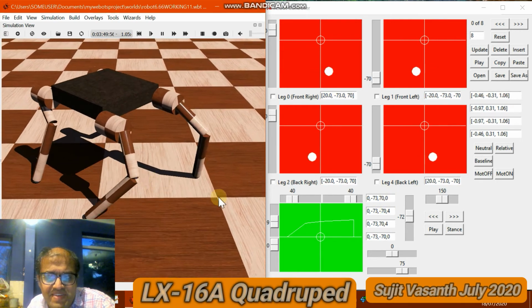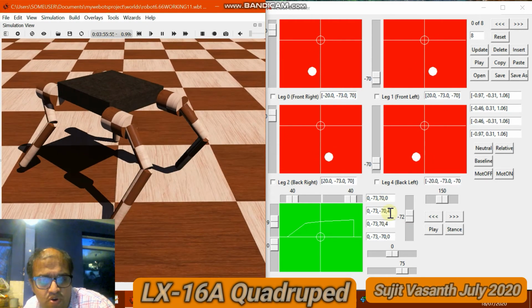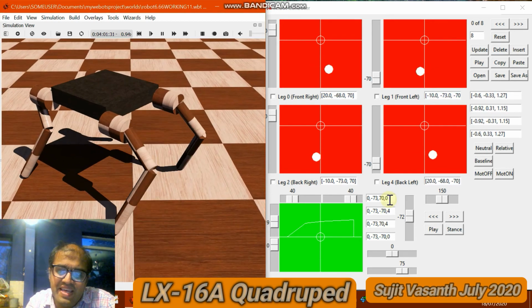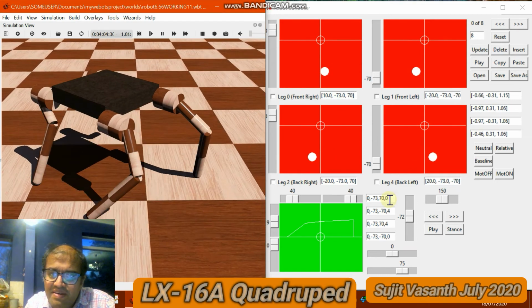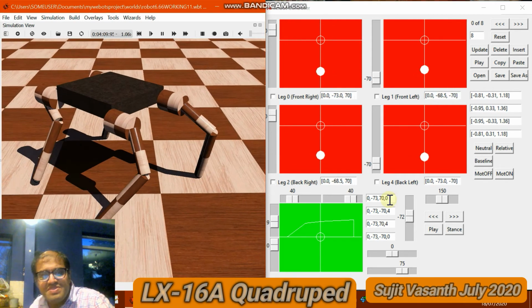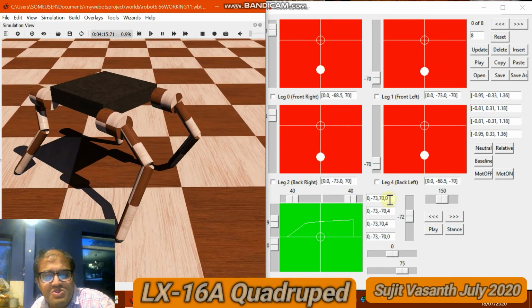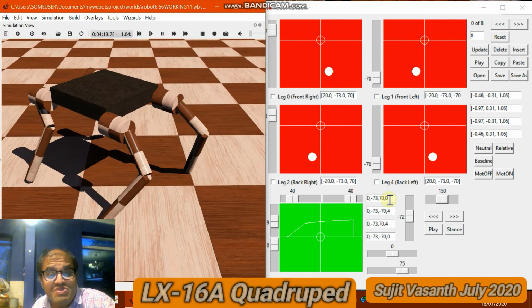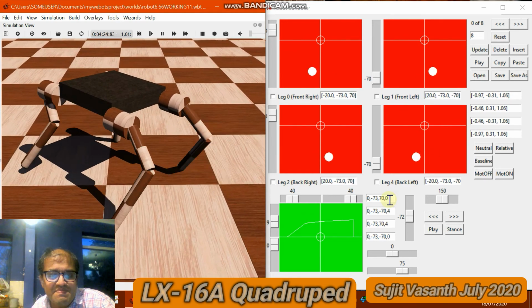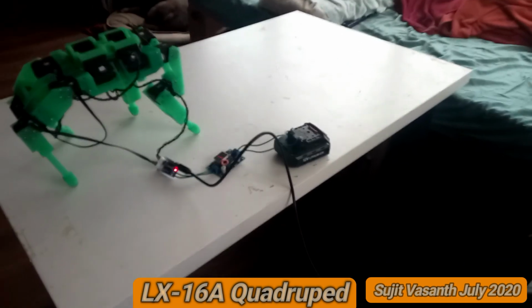In this particular set of gaits, there's 8 phases, 0, and then the counterpoint is 4. So you've got the front right leg in 0 phase, and then the back left leg in 0 phase, and then the other 2 diagonally opposite ones are in phase 4. If you switch those round, you can get trotting gaits or bounding gaits. So that's something that I'd like to experiment with in the future. This is the first walking of my robot. So here we go.